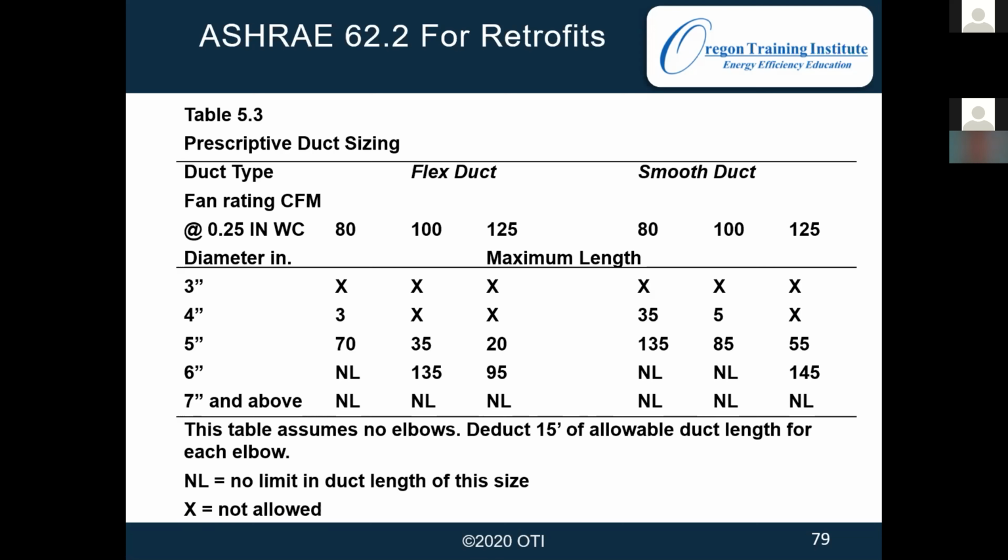That's going to use more electricity, so it's going to cost more money than if we had just vented it out better, not causing that restriction in the first place. So even though there are some fans that can ramp up, when they do, it's going to move the same amount of air, but we're going to have to pay that penalty. So it's better just to vent it right in the first place than rely on it to keep ramping up to try and move the desired amount of air.